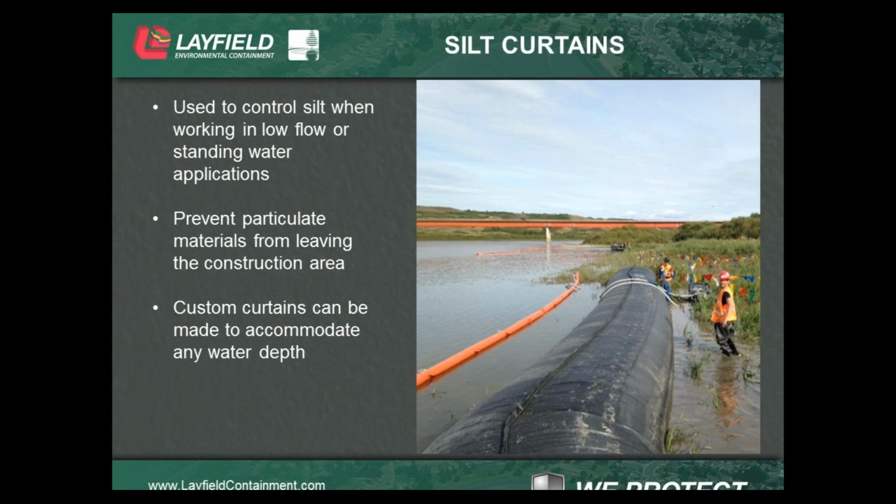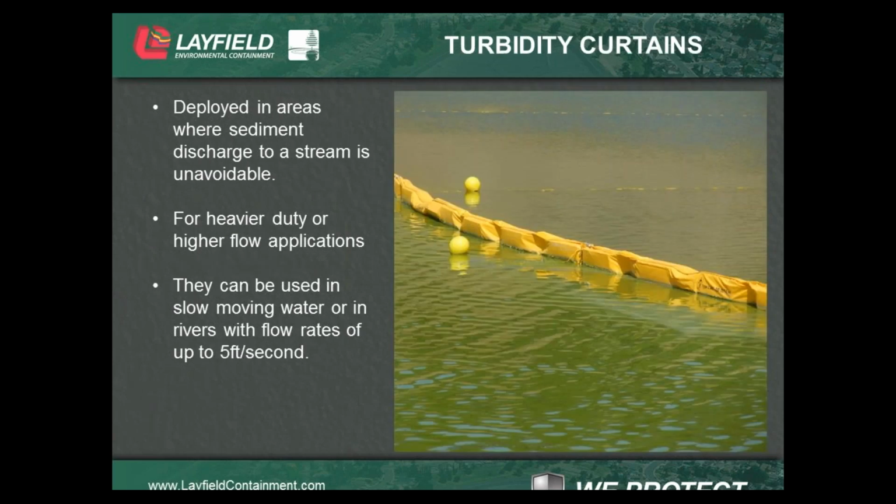Custom curtains can be made to accommodate any water depth that you might have, and in addition to that, even custom lengths. If you require a custom length floating silt curtain, we can absolutely do that as well. So just a few little things. A silt curtain is much more of a shorter term use than what a turbidity curtain would be. A turbidity curtain is deployed in areas where sediment discharge to a stream is unavoidable.